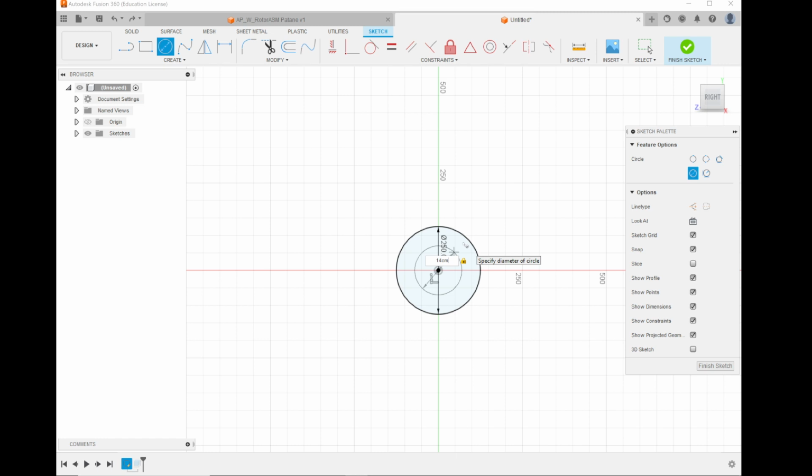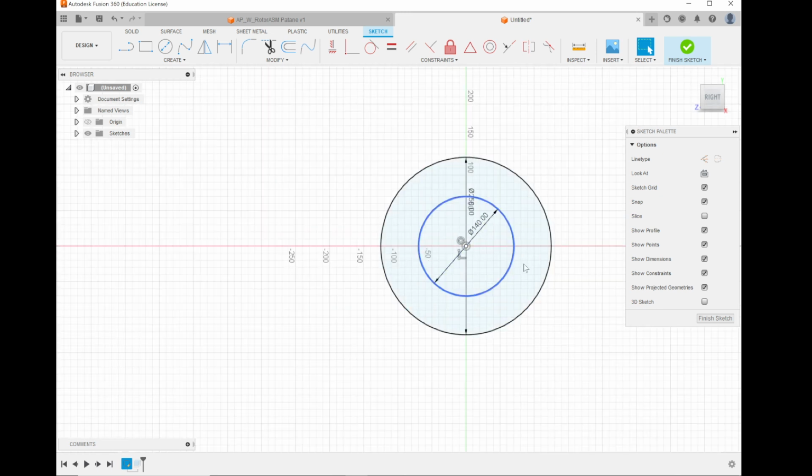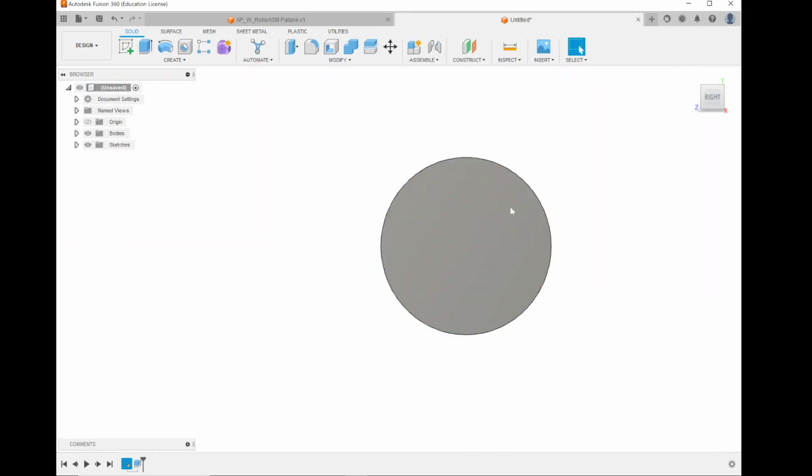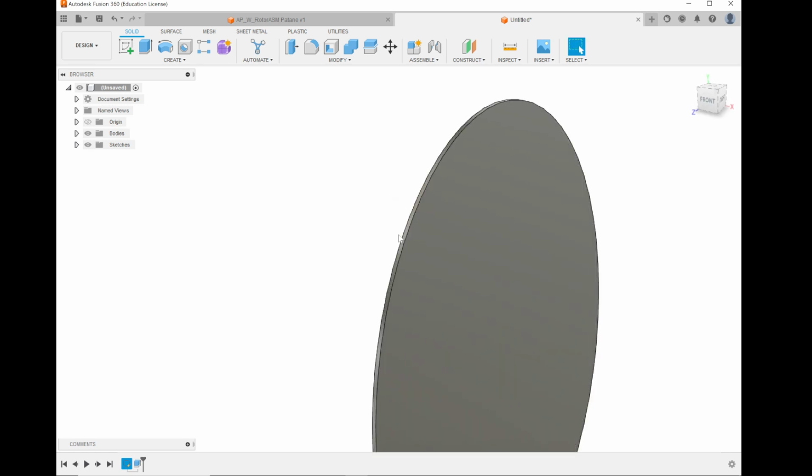This is really useful, especially if your design is using inches, like if you're putting in an imperial unit in there for some reason, or you want to put in meters, millimeters, centimeters. If you write in the unit when you're doing the dimension, it will automatically scale that for you. That's quite useful. Now, this over here is 2D, but when I press Finish Sketch, it automatically changed the drawing to match it. So now it is looking like the thin part of the brake that I want.